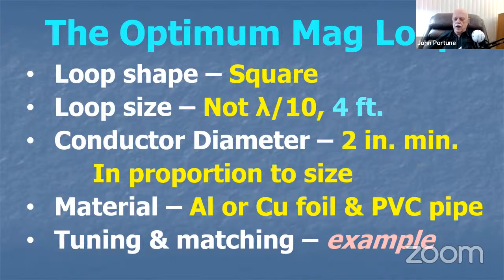And it has to stay in proportion to size. So if you make it an 8-foot loop, it has to be 4 inches in diameter. Make it a 16-foot loop, it has to be 16 inches in diameter. Otherwise, efficiency will go in the dumper. And the material, don't make it out of copper or aluminum. Make it out of PVC and foil. That's the efficiency. That's the optimum loop.